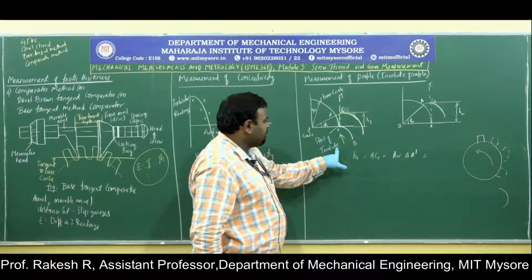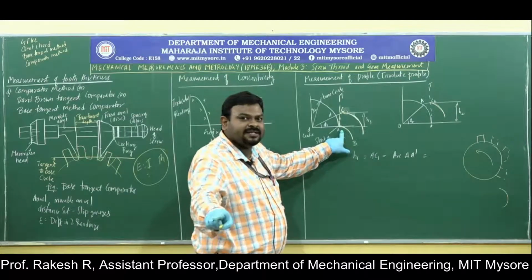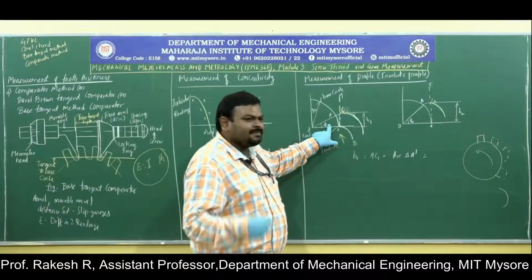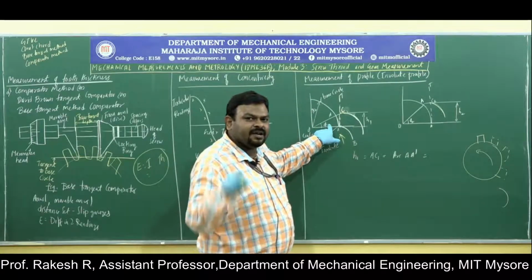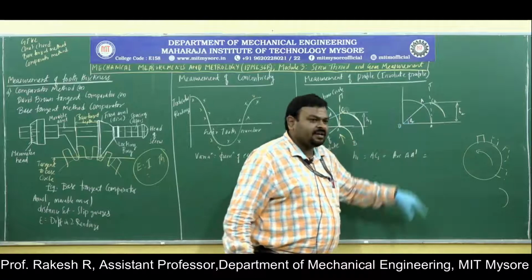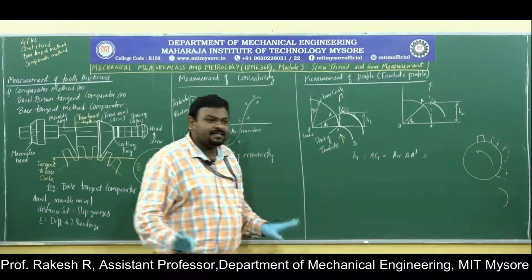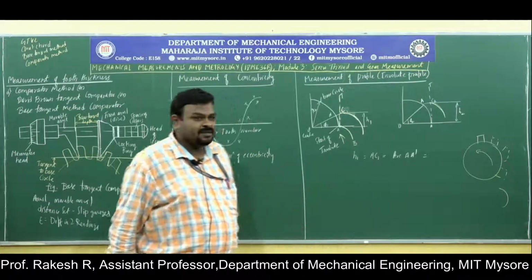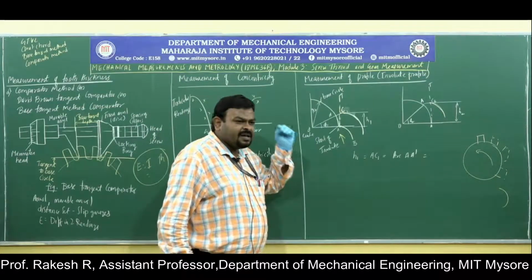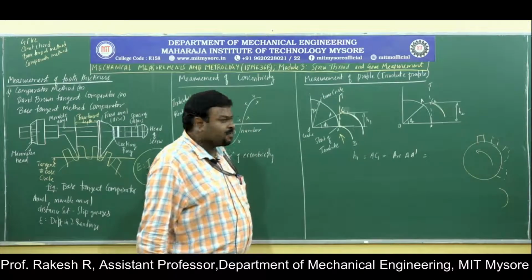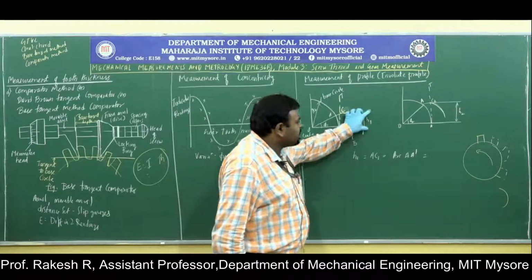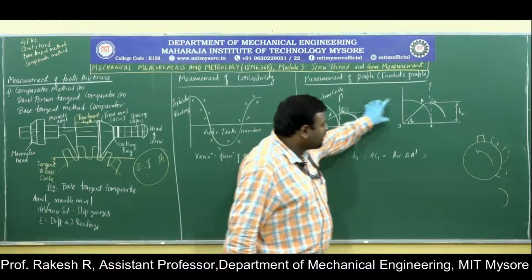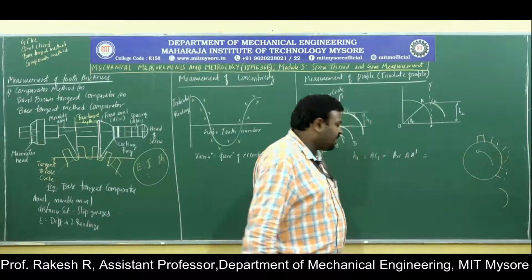And this is the starting point of the involute, that is the first tooth point, and this is the second tooth point. So I have measured the angle as phi 1, the pressure angle for tooth 1, phi 2, the pressure angle for tooth 2. Basically the pressure angle, theoretically speaking, should be constant for all teeth. That is a condition we will follow here. Let us see what the thing is. So I need to calculate H1, that means for the involute, how much distance I have to move. H1, H2, H3 I need to calculate.